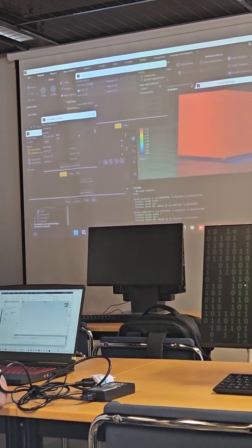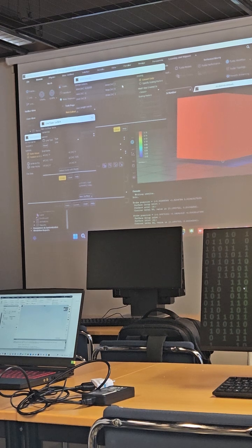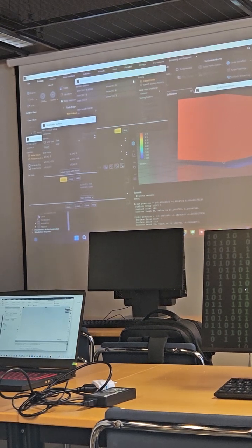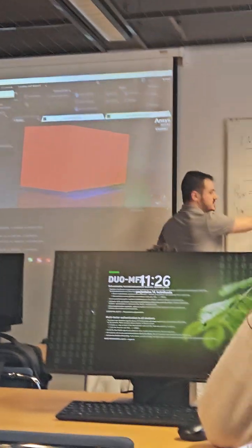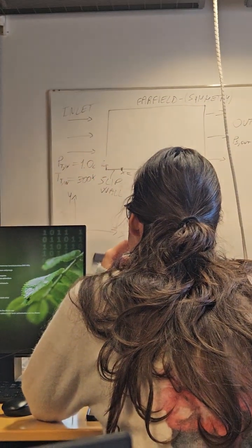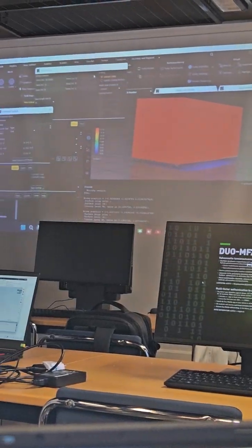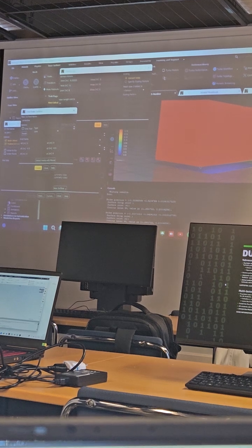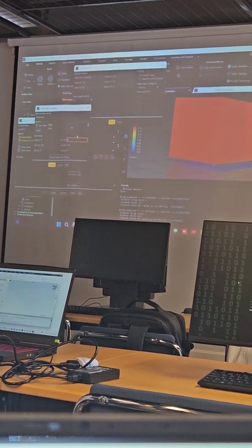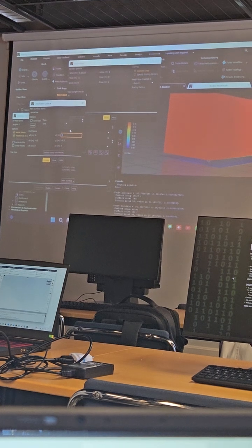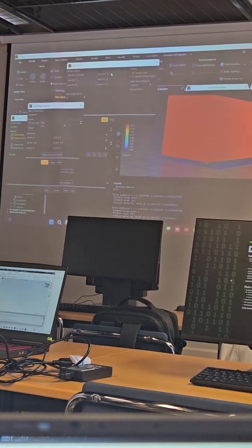The x goes from minus 0.33 to 2, but the part that we are interested in, the non-slip wall, starts at x equal to 0. So we set x0 equal to 0, and x1, that is the other endpoint, equal to 2, the maximum extent.